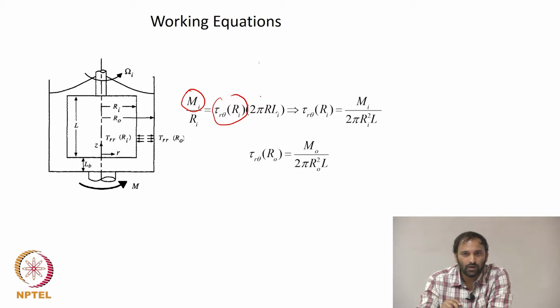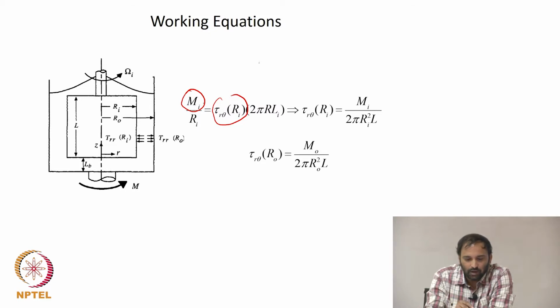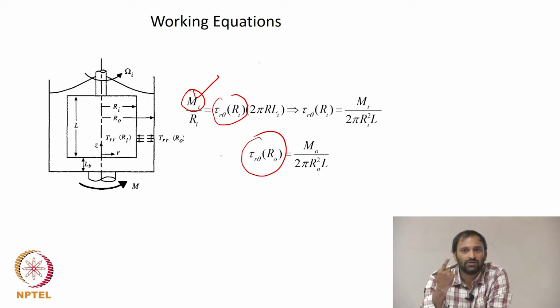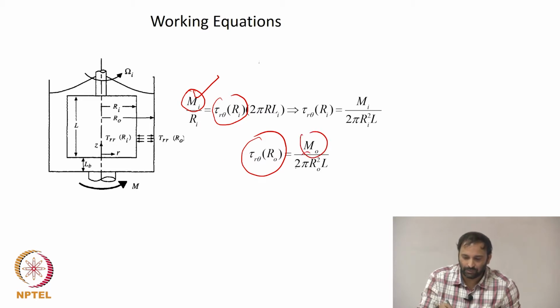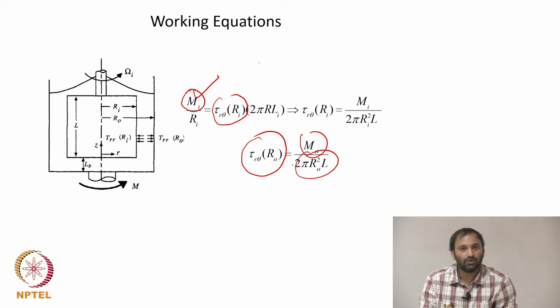Therefore, because I'm measuring the torque that I'm applying, I have a way of calculating the shear stress. Because I know what I'm applying and I know the dimensions, I can get your tau r theta.